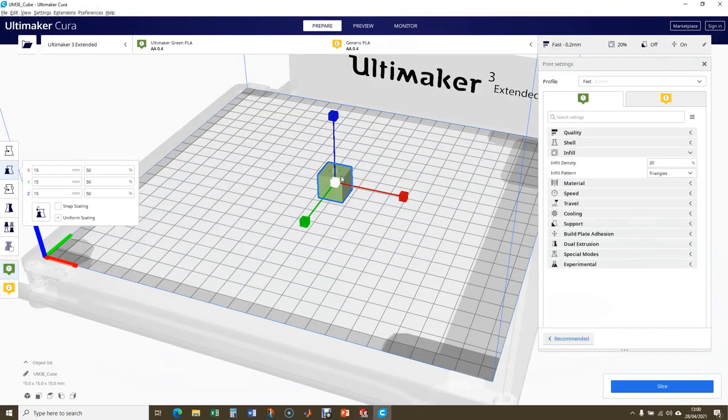Okay, so be very careful about changing the dimensions in here by just scaling. If it's just an ornament or a decoration, right, it makes no difference. So we can scale it up and down all we like. Okay, but if it's a part for an assembly, you're better off to go back in and change the dimensions or scale it in CAD. Okay, so you can make sure the clearances are the same.